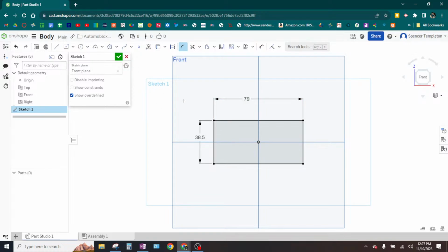Now, let's click the corner of that. When you do your fillet in a sketch, you don't click on a corner. Well, I guess you can. I clicked on the dot. You can click on two edges as well, like an edge and then an edge. Or you can just click on a dot. Do I leave it default? Are we supposed to do every corner round? Yep.